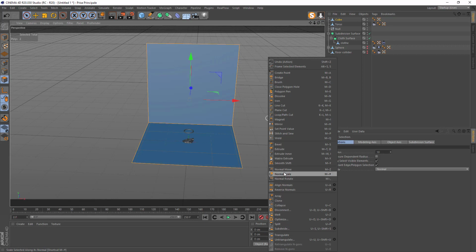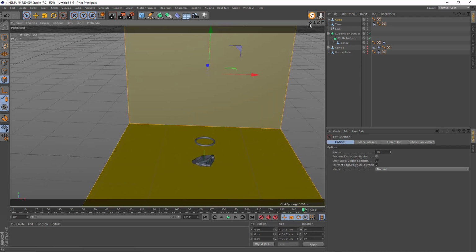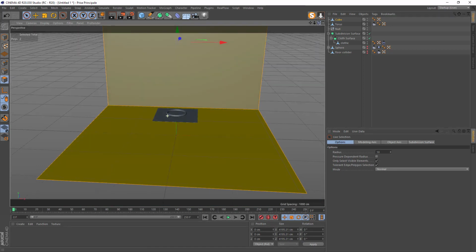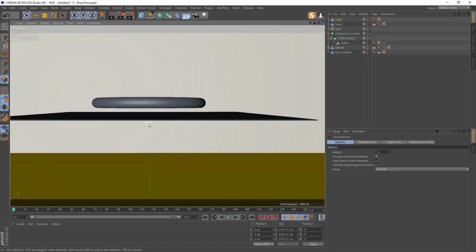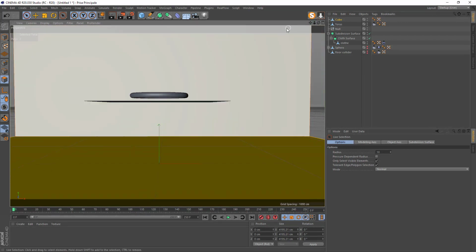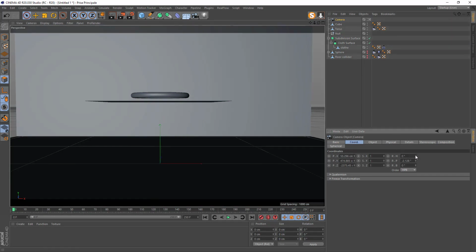We will place a camera. So go maybe to the first frame. Add a camera, go to camera view, click on the camera, reset this value. This value put like -10 and go up like 600 and zoom.